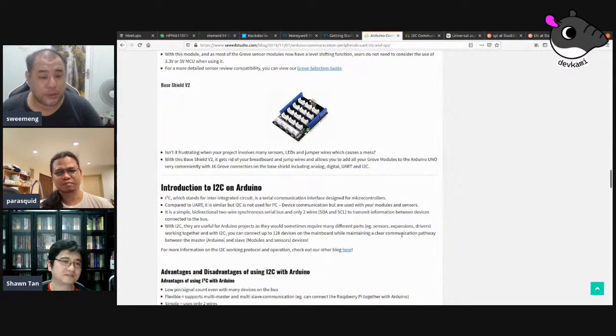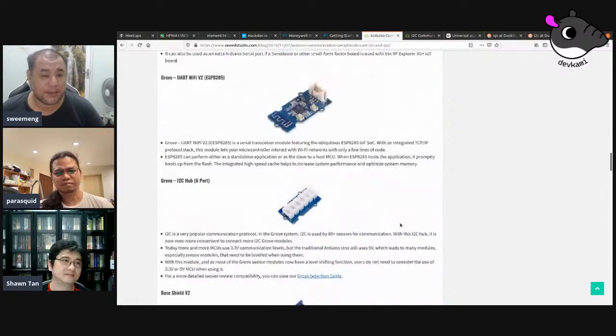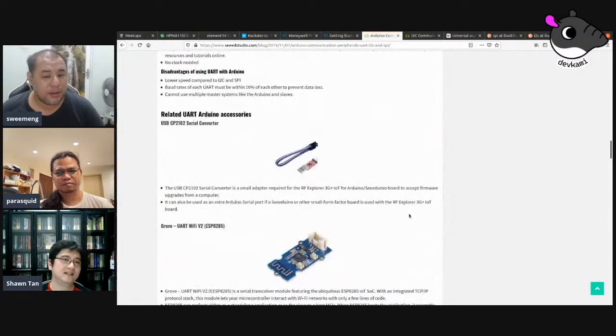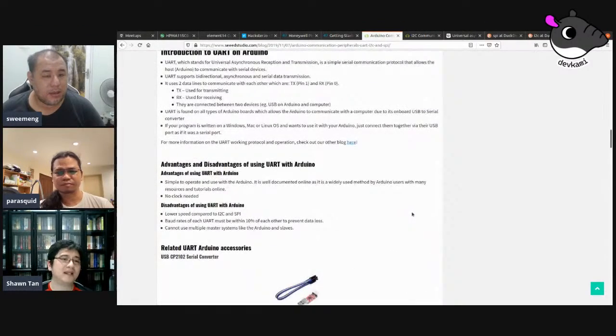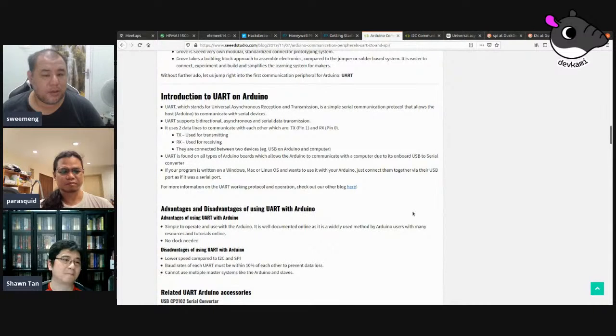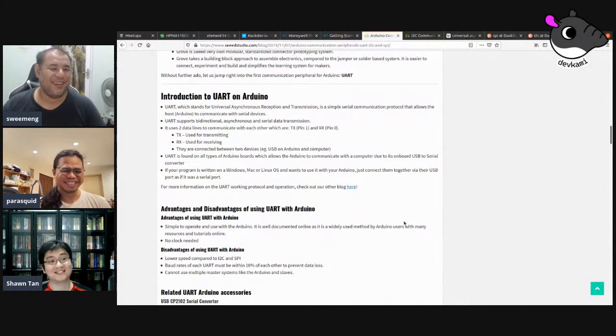The next one that we actually commonly use is UART. This is serial. UARTs are mainly used for machine-to-machine communication. So less for sensors, but your microcontroller to another microcontroller. Usually, it's used for sending JSON, right? Yes, you can use it to send JSON, from microcontroller to microcontroller.